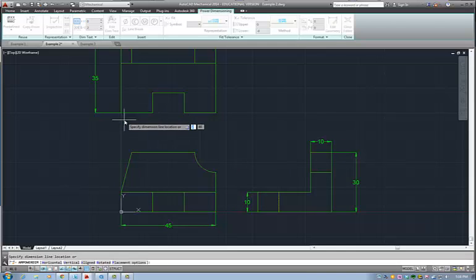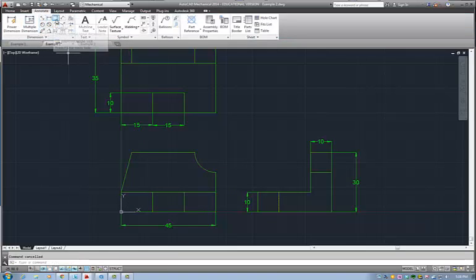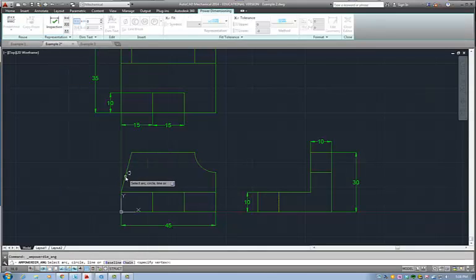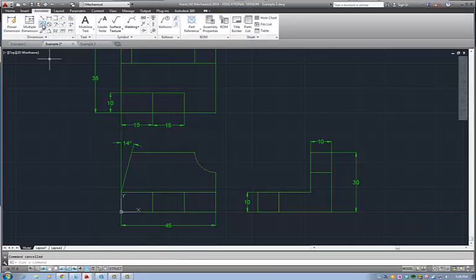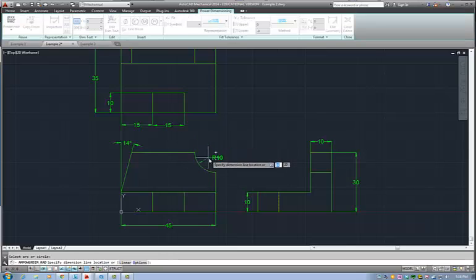So I can measure this, and here what I removed. And then I need a height for this one. I can put it either here, or I could put it here to the right. And in terms of this one, here actually I would like to measure the angle. So I can select here the angular. Here I click on the line and the other line and whatever angle I have here. And here I would like to measure the radius. And this is all I need for this drawing, basically, nothing else.